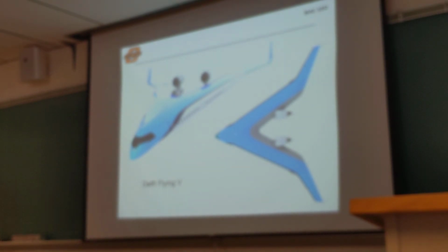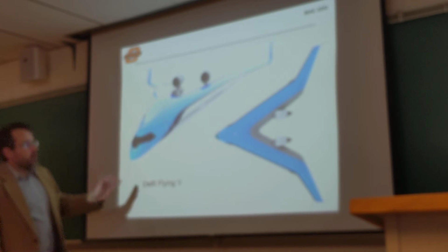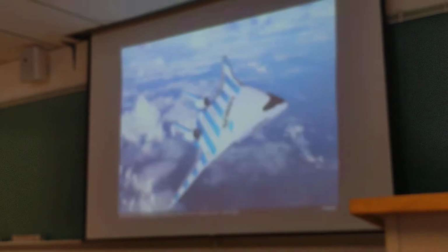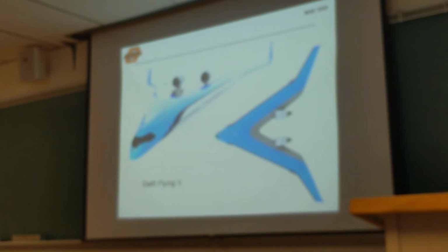So if you plot this overall and look at how the area ruling behaves on both this body and this body, you actually end up with really nice area rule profiles for your aircraft without having to go through the process of adding stuff like shock pods to be able to counter things. But can you actually get someone to fly on it is another question. There's got to be a brave few that's willing to take that.